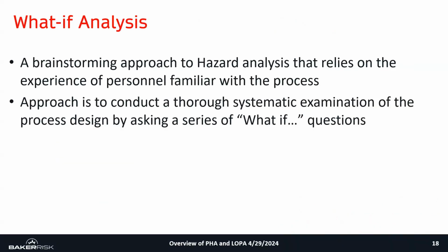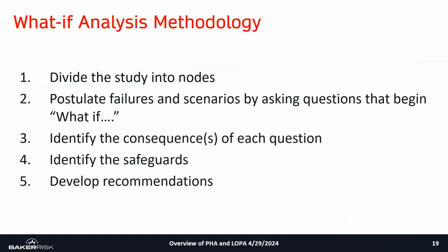Another common one is what-if analysis. What-if analysis is essentially a brainstorming approach. It's important that your team is knowledgeable in the process, which is really true for any of your PHAs. You want to have personnel that have working knowledge of the process hazards and how the process works. But in the what-if approach, basically your team will divide your study into nodes. Basically that means breaking your process into different sections and then evaluating each section by section.